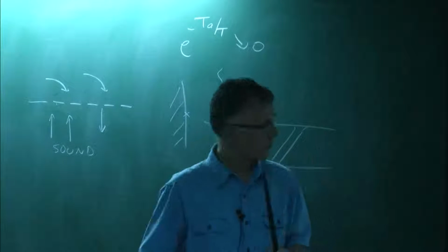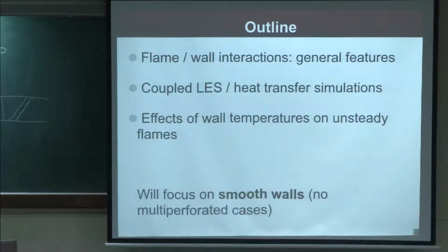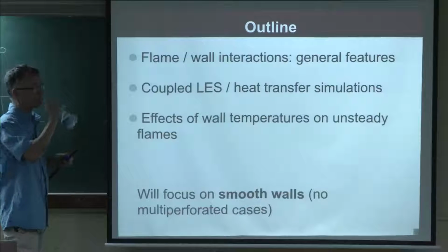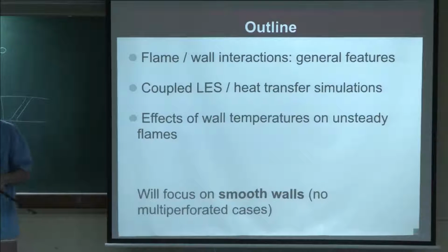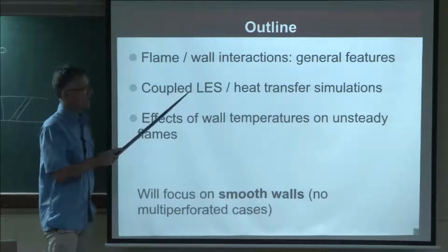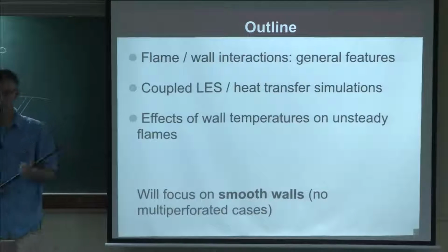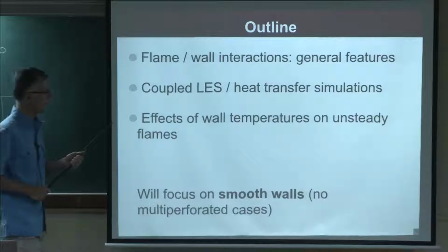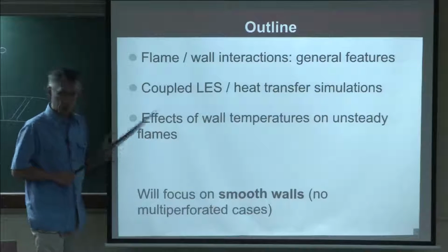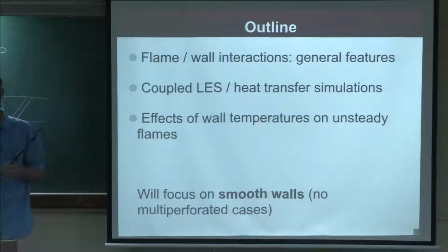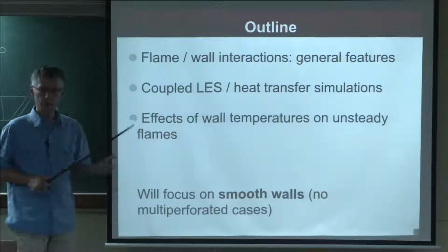So, what I want to do now is to start discussing flame wall interaction in general, and you will see that what it really leads us to is to build simulation where we can do the LES of the flow and the heat transfer at the same time. That's the most important thing. And I will give examples then of different studies where wall temperatures play a very strong role on flame, and that we need to include that in our description.